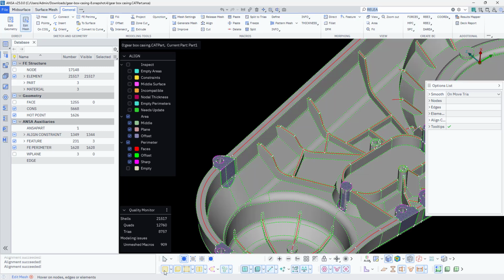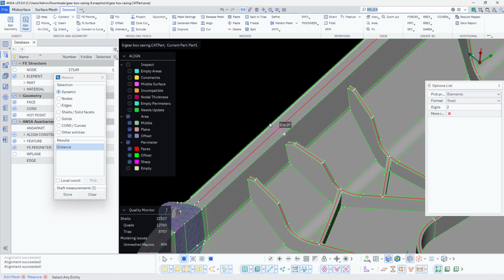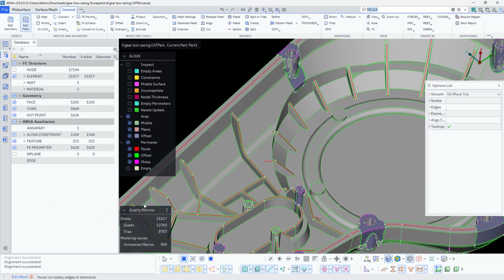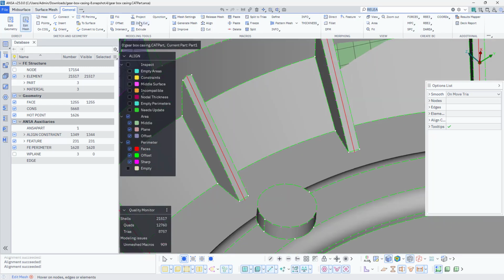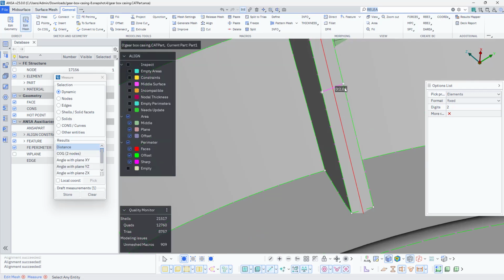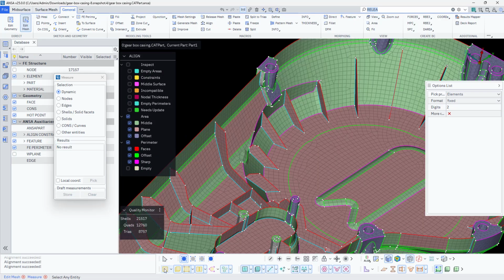Now I'll just activate the CAD and you could see this is the CAD. I'll just use the measure tool and I'll measure the distance from here to here. It is exactly around 6, right? Fine. And for the ribs also you can measure the thickness. So here it is 1.8 for the ribs, and for these ribs let's measure it. It should be, oh, it's 2 mm. Yeah, so we got to know the rib thickness.